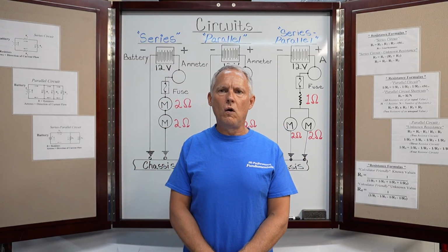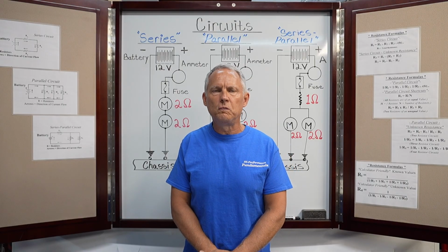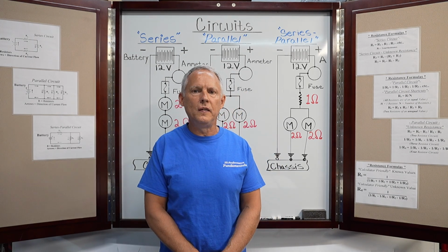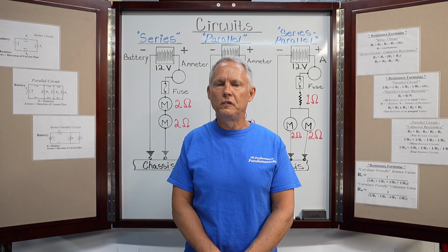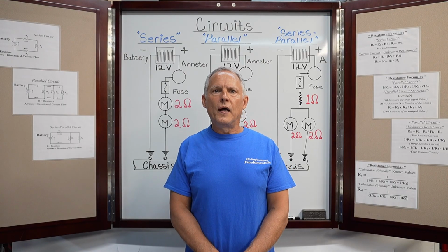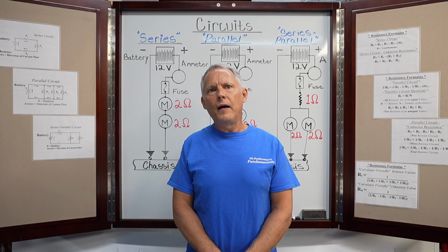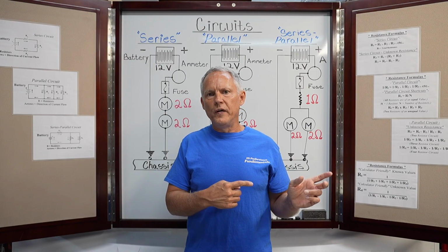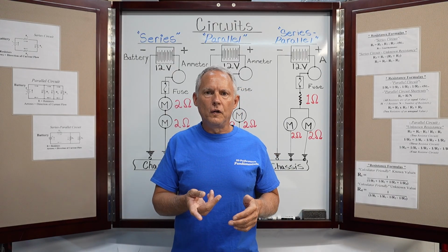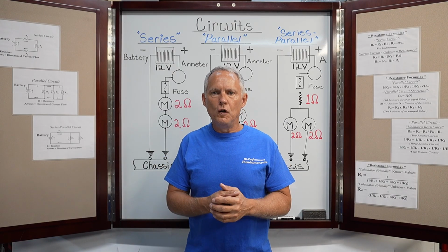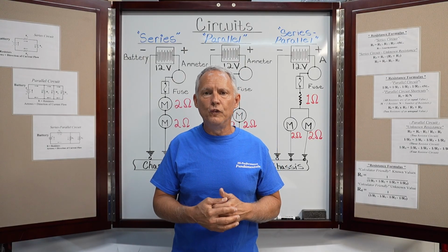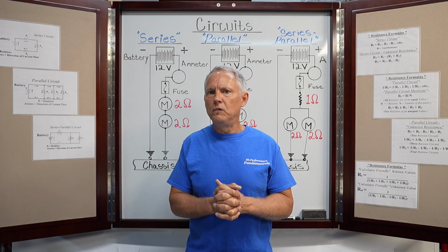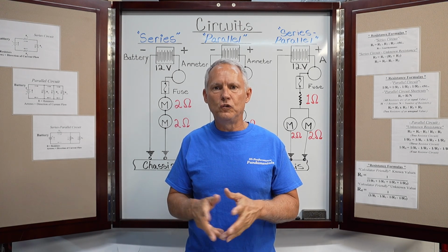And what I found was that on a lot of the European, German models, the Japanese models, the specification that I gave, 52 to 56 degrees, is pretty accurate. But then I got to looking at the American-made models, the Chevrolets and the Fords. Not even close. Okay? So, like I said, although at this point I kind of wish I wouldn't even have brought all that up, just to clarify, 28 to 32 degrees on a V8 is close. On a 6-cylinder, 34 to 38, that's fairly close also. On a 4-cylinder, I had said 52 to 56, and on a lot of the European and Japanese models, that would be pretty accurate, but it sure doesn't cover the domestic manufacturers, the Chevrolets and the Fords.